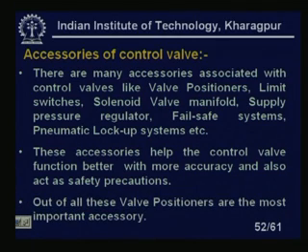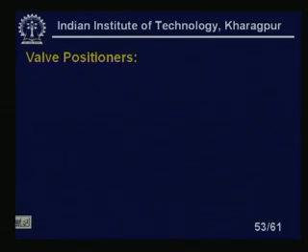Out of all these, valve positioners are the most important accessories. So, we will study the valve positioners in detail. Clear? Now, valve positioners. What are valve positioners? As the name implies, it will position the stem, the plug on the seat of the valve more precisely, in a much better way, so that there is no hysteresis. The valve positioner is necessary due to the hysteresis. We will first look at what control valve hysteresis is, and the need of the valve positioners.